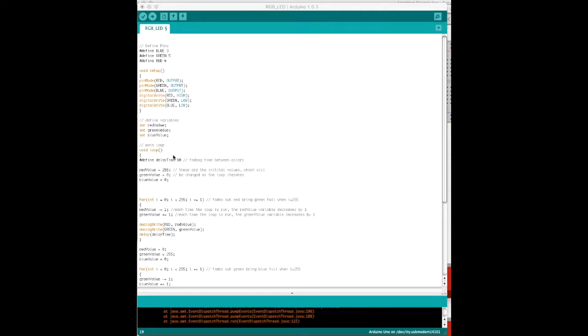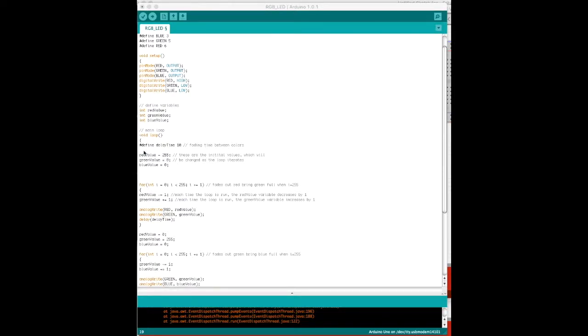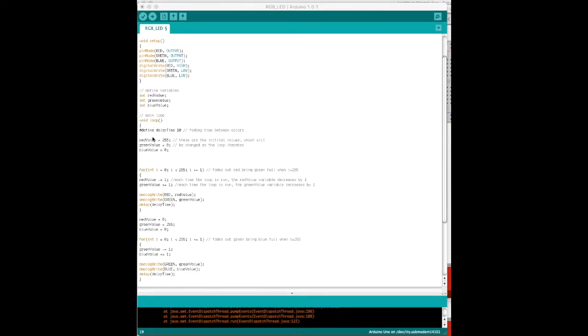So now that you have that done, you can do the main loop. Have you ever noticed on an Arduino, whenever you plug it in and run the program, it just runs the program over and over and over again until you unplug it, or I guess if you were hooked to a battery until the battery ran out. That's because you have a main loop called void loop. And that loop is just going to execute everything inside of it, and when it's done, go back again and keep going, like a loop.